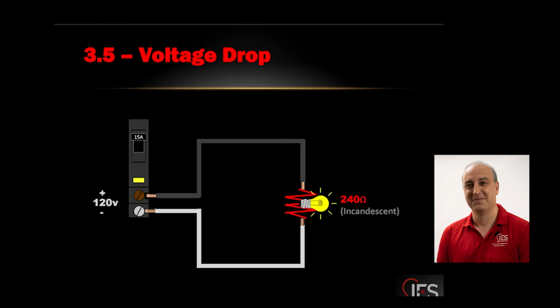What I want you to understand from today's lecture is that we don't have negative and positive here really, because it's constantly changing. So the negative and positive is determined by the power generation at the power plant, and is pushed all the way down through transformers to your service and here. So when we put one plus and minus on an AC circuit, we're only saying that this is a starting point. But your hot and neutral both bring in electricity. That's why there is this misconception that neutral is safer than hot. You should drop that very quickly, very early on.